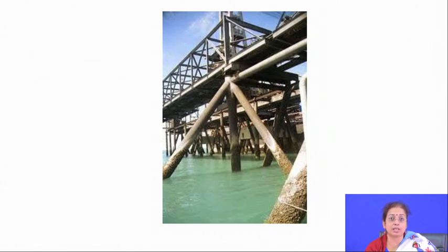So, what you have to do is that at regular intervals you have to inspect the corrosion rate of the corroded species, corroded magnesium, so that you can say whether your steel can be protected further. Otherwise, you can also estimate the amount or volume of the magnesium required for protecting the component for several years, or accordingly you can also calculate the lifetime of the component.